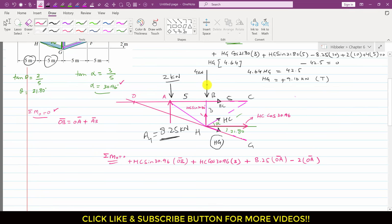And this 4 kilonewton force is producing the clockwise moment about that point O, so I have to write minus 4, and the perpendicular distance or the moment arm of this 4 kilonewton force from that point O is the summation of OA and this 5 meters AB, right? So this is OB length, and OB is equal to OA plus AB, where AB length is 5 meters, so we can write it like this.